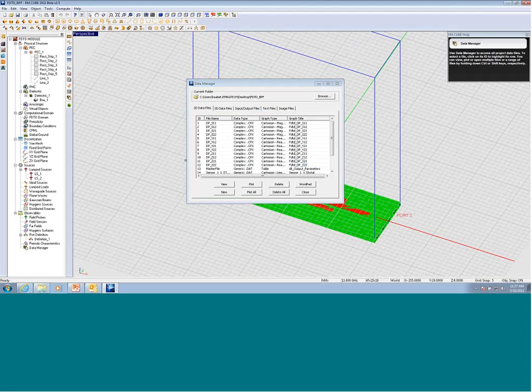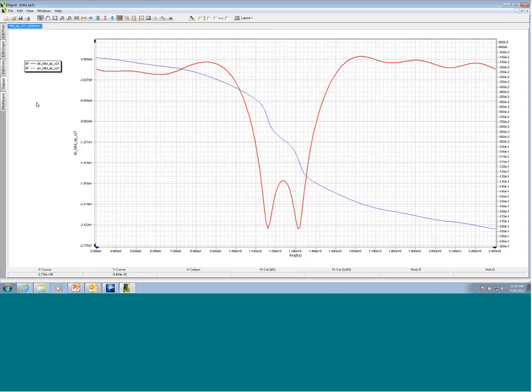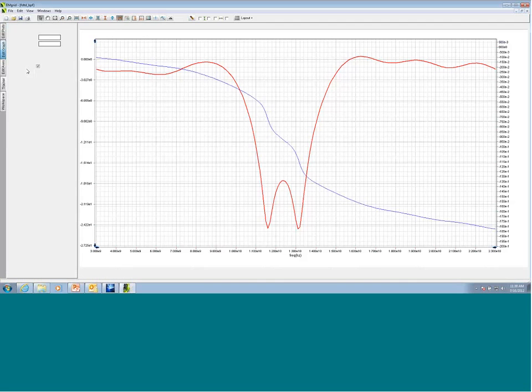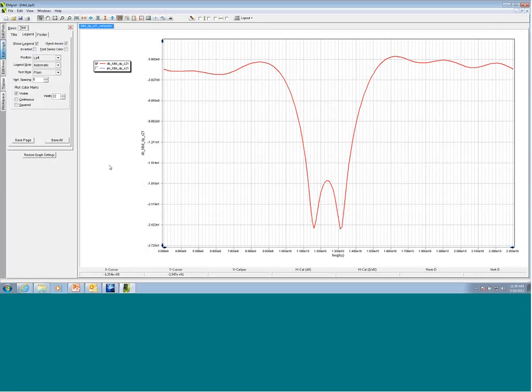So we can look at a lot of things, including S11, S21, but for a filter, what is interesting is the insertion loss, or basically the filter characteristics, S21. So we look at the plot, and the blue is the phase, and the red is the magnitude. So this is the magnitude of S11. And you can put the crosshair here and measure. Like here we have minus 18 dB and minus 24 dB here. Okay. So we go back to the presentation.